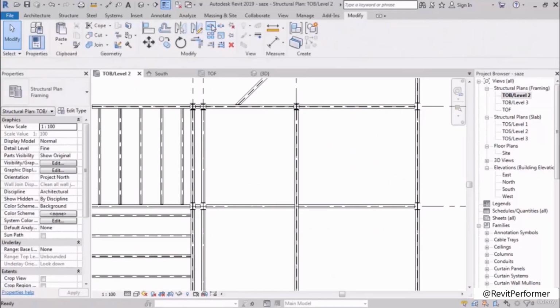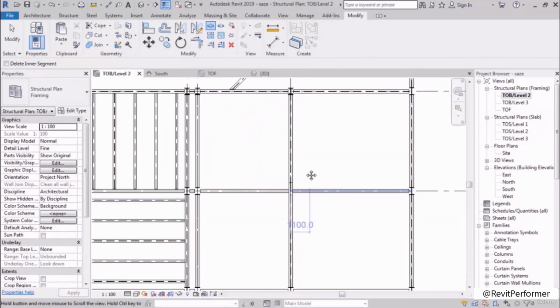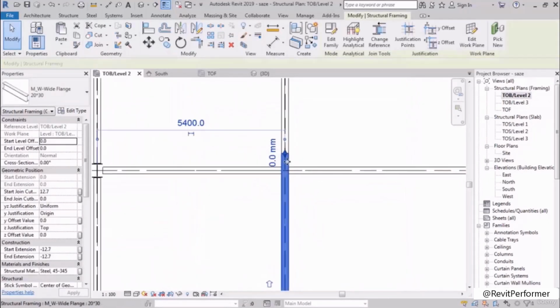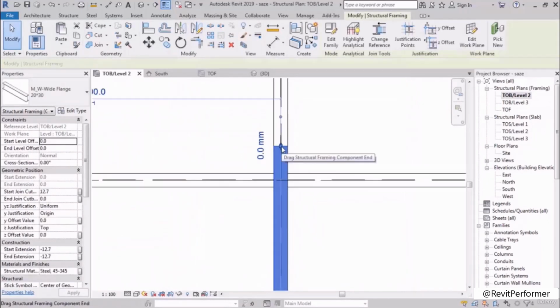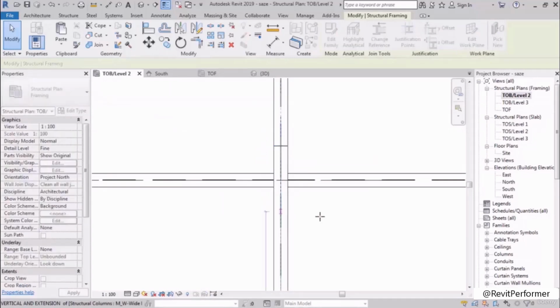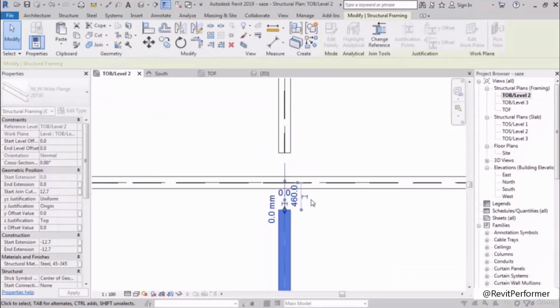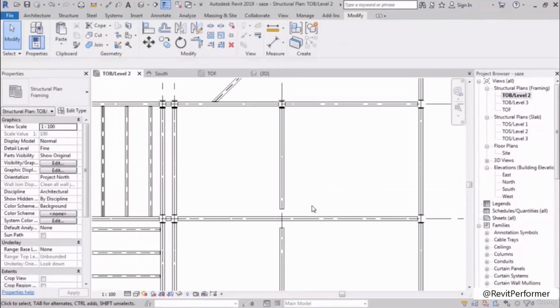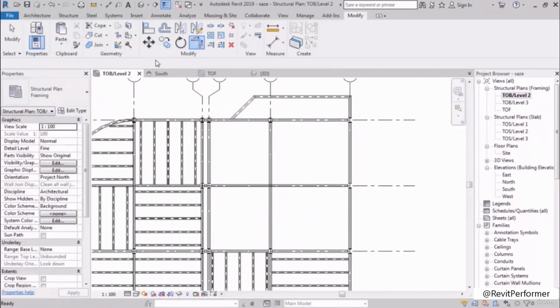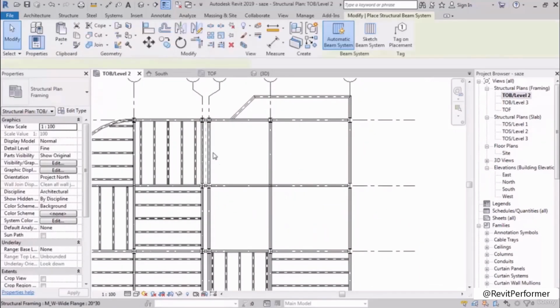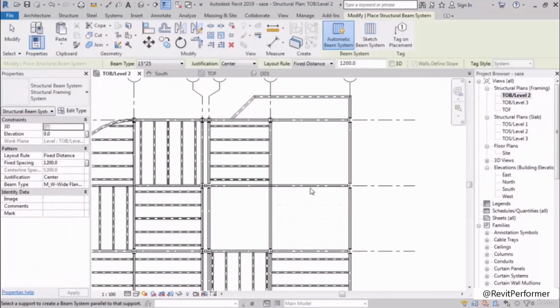At first, you're going to have to split this beam that is flat, right? Split it somewhere, doesn't matter. But hold this spot, not the arrow, hold this spot and drag it back, right? And then you trim these two. Now, just what you see, there's a gap here. You see that? So trim these two. It's usually fixed. Yes. You see that?